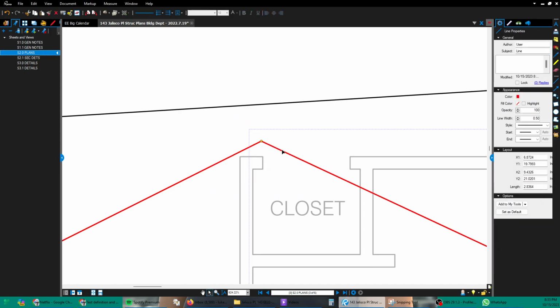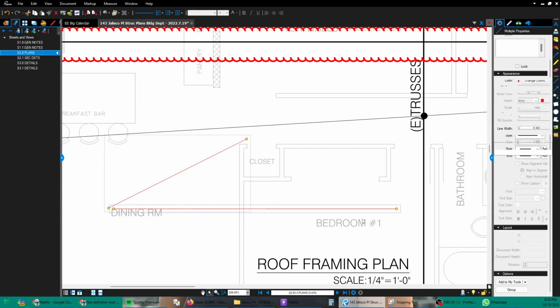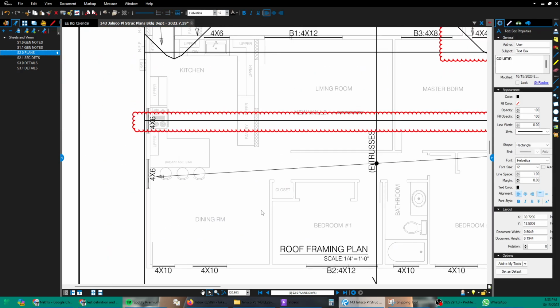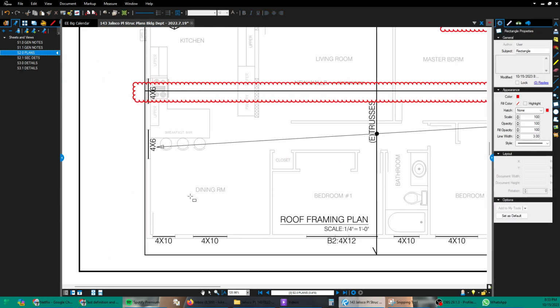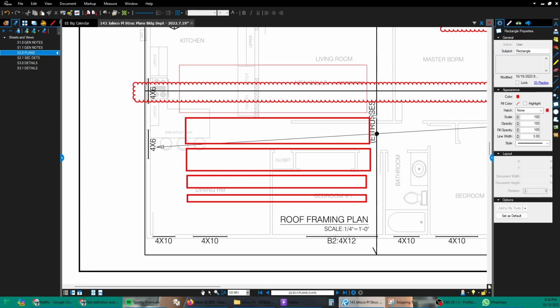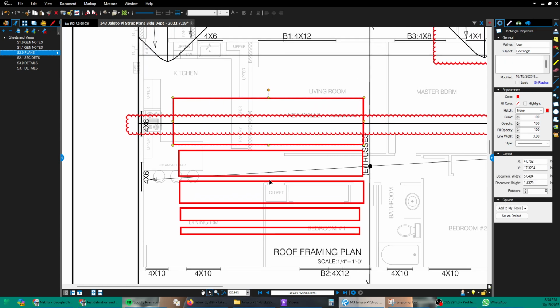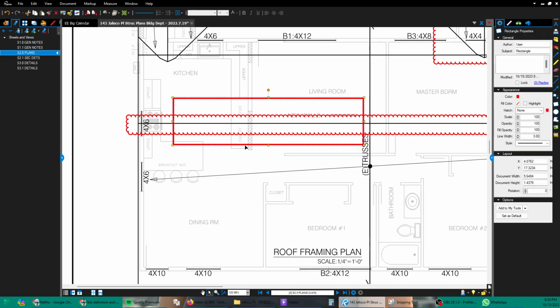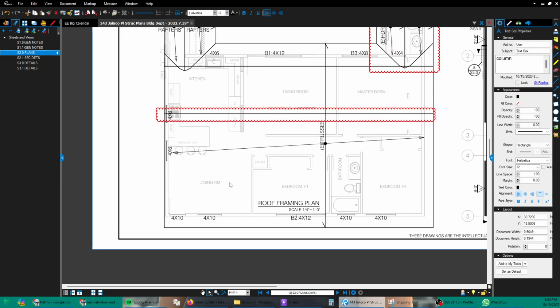If you were going to try to do it the other way, so that the trusses were parallel to the ridge, you can go through that thought exercise. You'll have to have a truss, and then the next truss over will have to be slightly taller. The next one over will have to be slightly taller than that, and so on. I'm just drawing these side by side, even though that's not exactly how they'd be installed. But every truss would be different from the truss next to it.